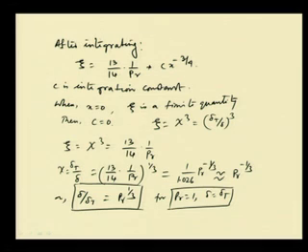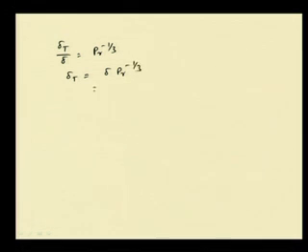Okay. Once we have the expression for delta, we have already seen that delta t by delta is equal to Prandtl to the power minus 1/3. Then delta t will be equal to delta into Prandtl to the power minus 1/3, and delta is 4.64 x by Re x to the power half, so delta t is 4.64 x by Re x to the power half and Prandtl to the power 1/3. So, this becomes one important understanding for us.